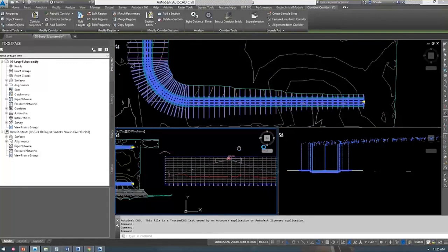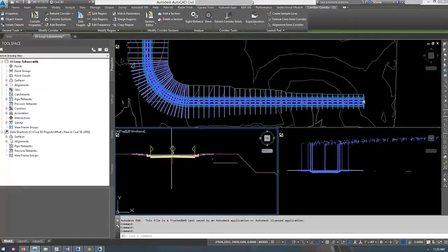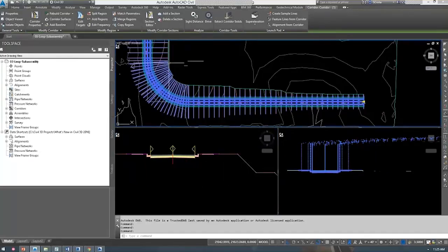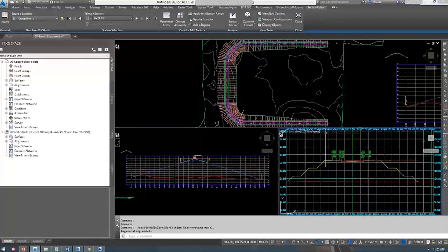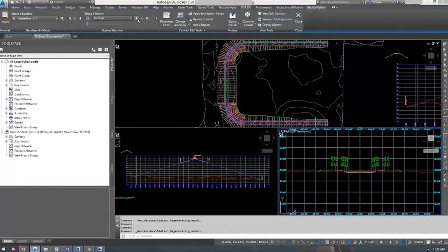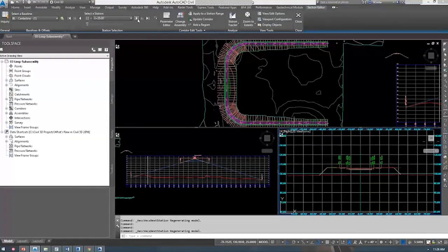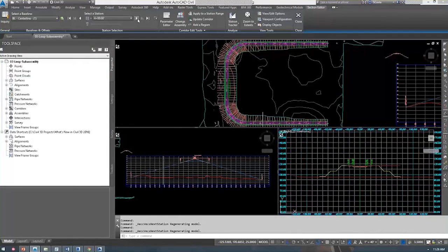using that, and let me just show you quickly, just an assembly with a typical road, some curb, a sidewalk, and then that loop. And you can see here that if I bring up my section editor, and I step through those, you can see here is what that looks like. And as I go back to the beginning and step through slowly, you should see there in the lower right-hand corner, as I move up grade, it's stepping through and generating that based off that loop geometry. All right?